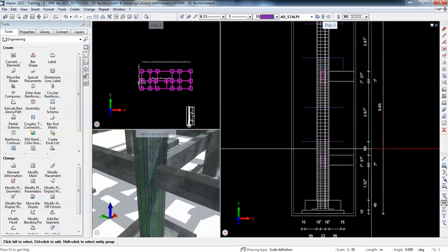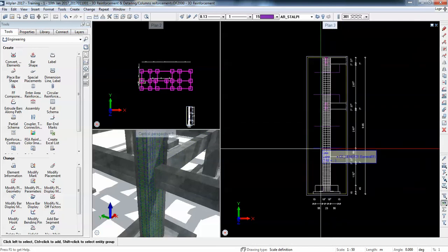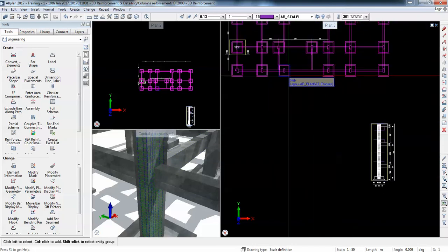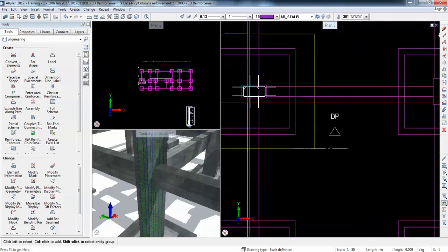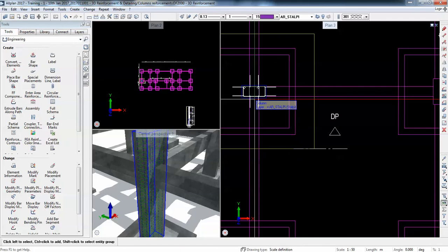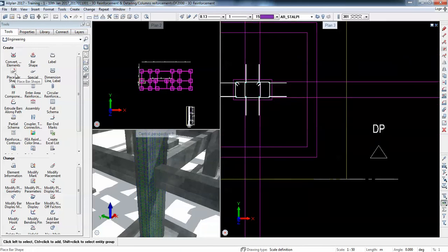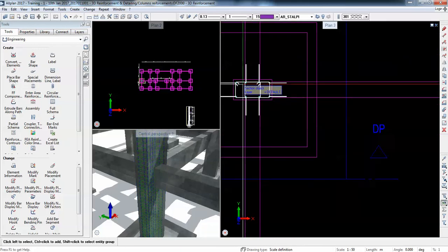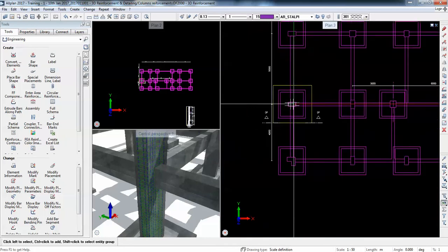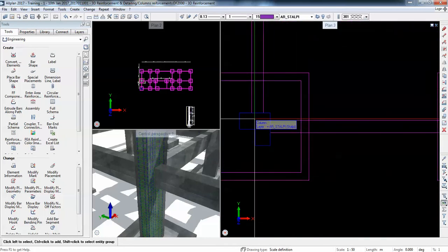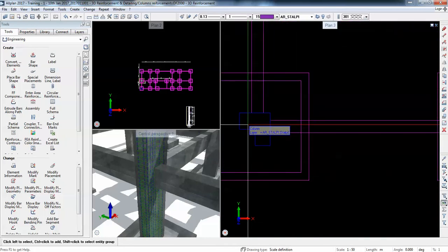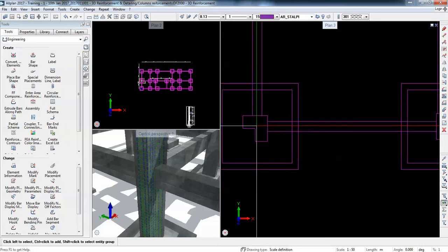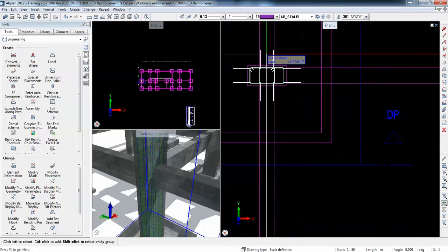Okay, as you wish. So I could have done this process on 2 types of stirrup at the same time. So I'll only redo the process now for this stirrup, but then I'll show you how we can reinforce the other column automatically with 2 stirrups at the same time. So we don't need to do those tricks. So we don't need to do the operation twice.